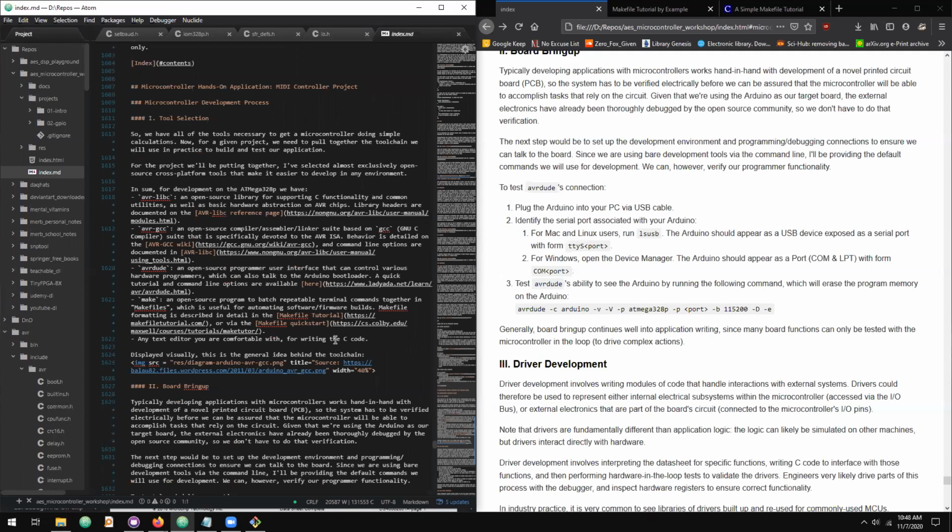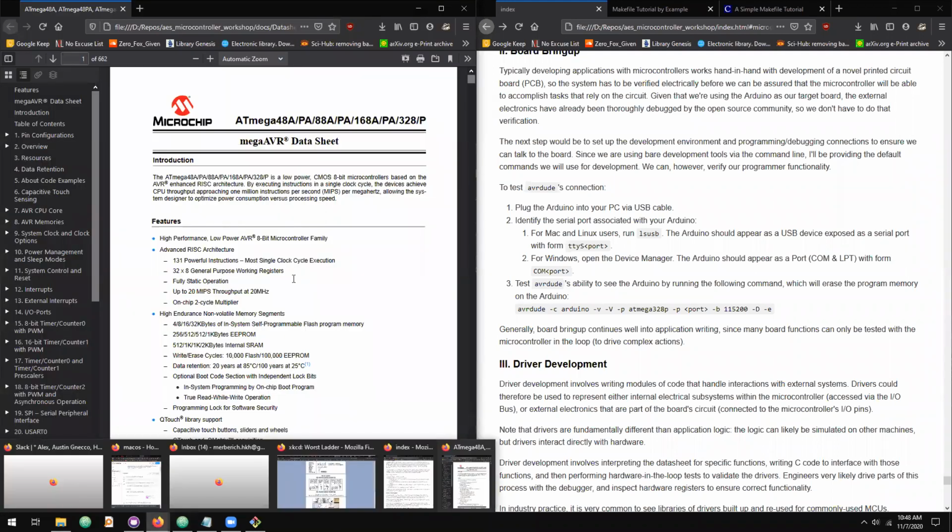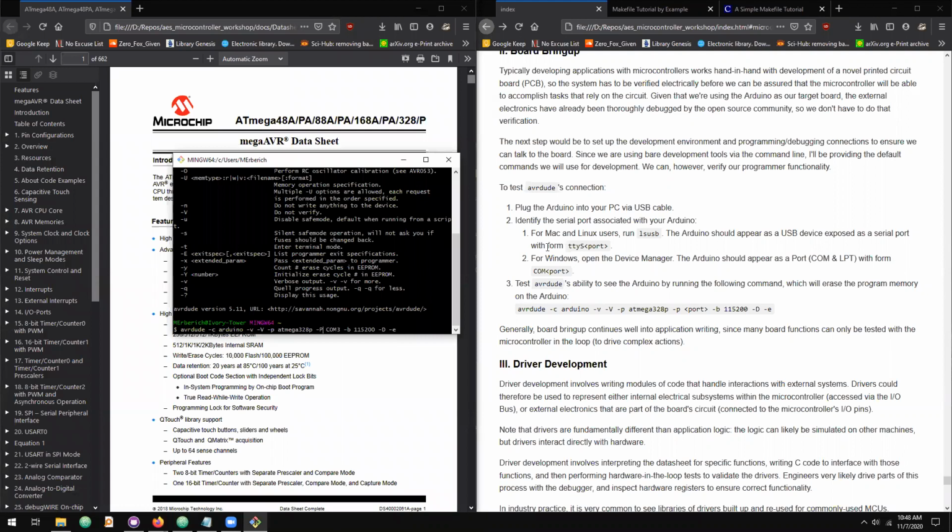The capital P lets you know which serial port you're talking to the programmer through. So for us, that's simply the serial port that our Arduino exists on. That's what we found via Device Manager or via lsusb or ls /dev/tty. So put that port number here.